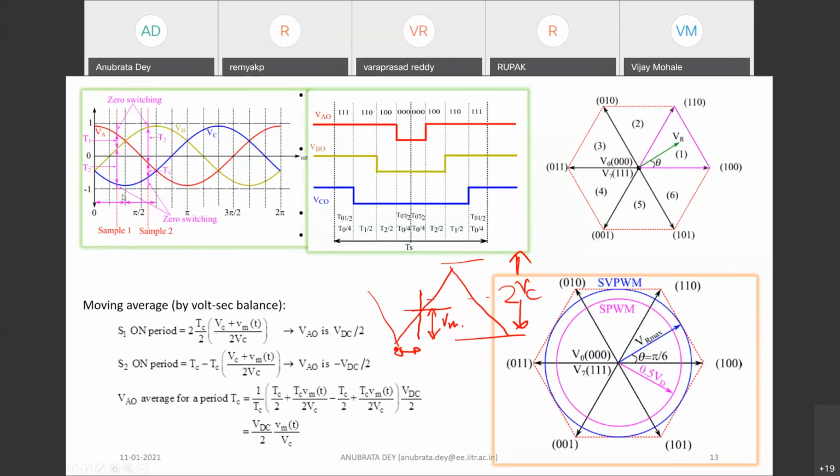So as you can see, if you look at this entire waveform, they are not very equally spaced. The envelope, if you look at the envelope, you cannot cross this +1 and -1 boundary. If you cross this boundary, you are actually entering into overmodulation. So you are not supposed to do that. But you have a different gap, right? You have a different gap. So in this case sample 2, the maximum value is VB, and the difference between VB and the 1 is this much, whereas the difference between this VC and this -1 is this much.